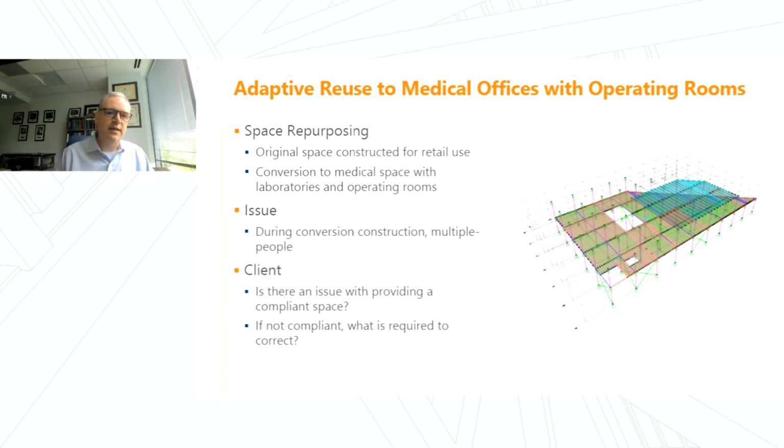In this next case study, we were brought in during a conversation about a retail building that was adaptively reused as a medical facility that included laboratories and operating rooms. The original building was not designed for vibration-sensitive functions. So the client raised an important question during construction, which arose in part because people were feeling vibrations when the design team visited the site. And they said, well, are felt vibrations okay? And so we were brought in to assist with that set of questions.